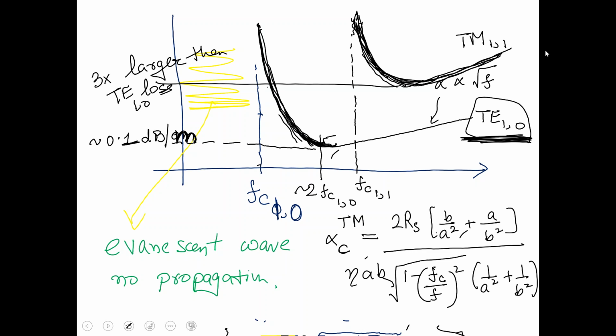That makes those cables very expensive, as opposed to rectangular waveguides, which could be made with copper or brass or even aluminium or even sometimes steel. People are even making waveguides with plastic and then coating them with metal inside to create the boundary conditions. So the loss at high frequencies keeps on decreasing.